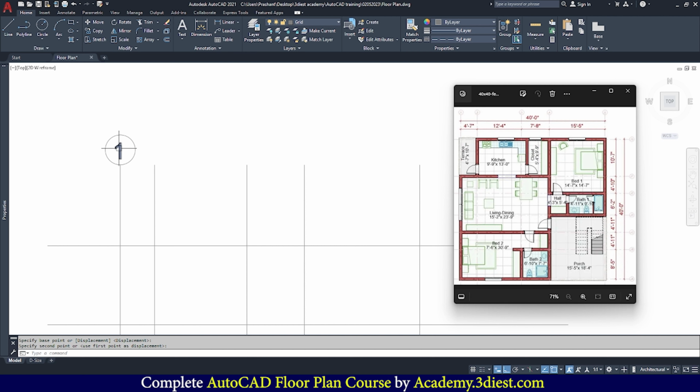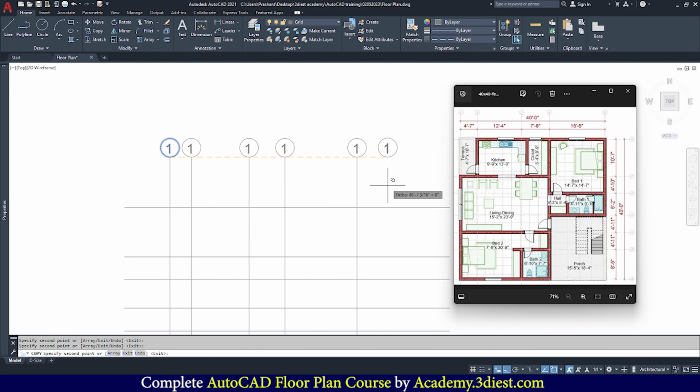For that, just select the objects. Here you can see I had selected both the objects. Then I will activate my copy tool, and specify the insertion point. I will select this end point of the line as the base point, and then keep clicking on the other end points of the line, and as you can see the copies are being created on every line. The moment I am done, I can just press Escape on the keyboard and we are done.